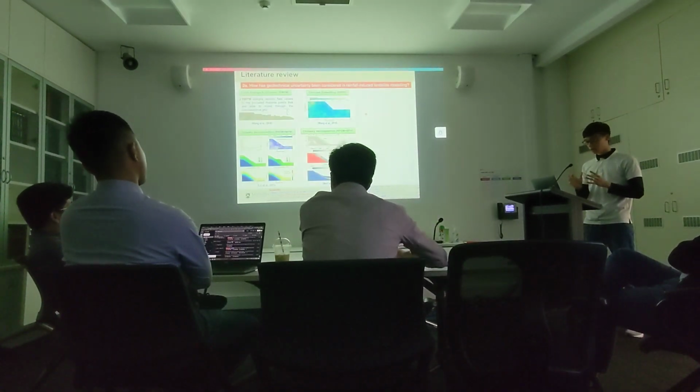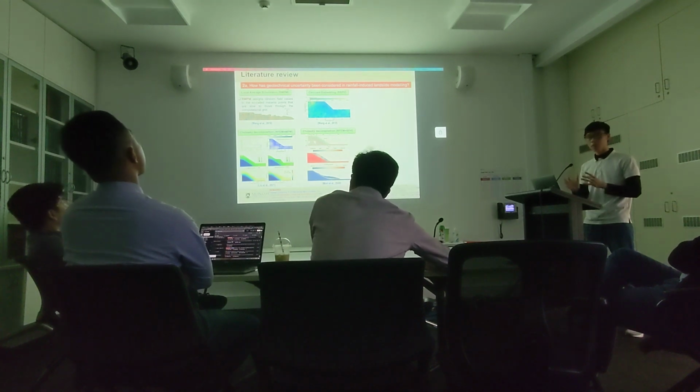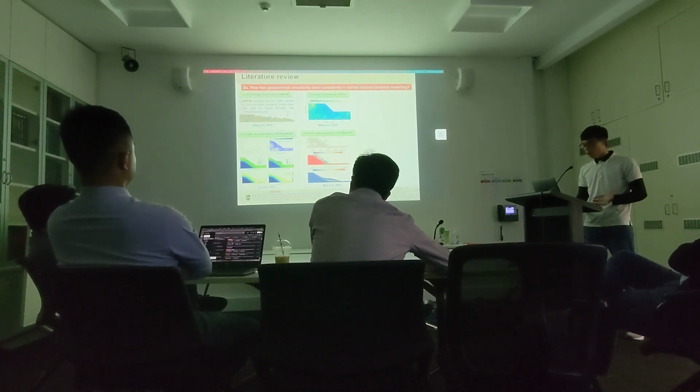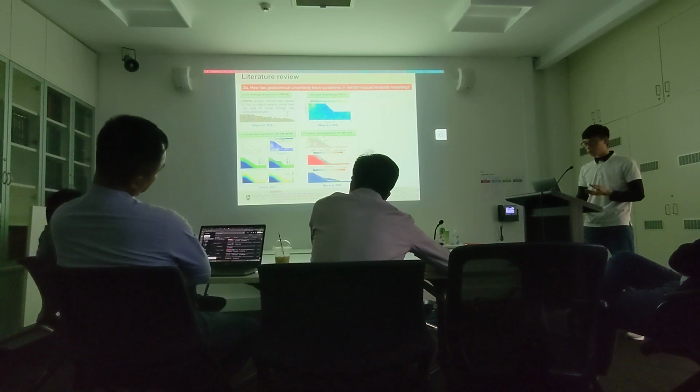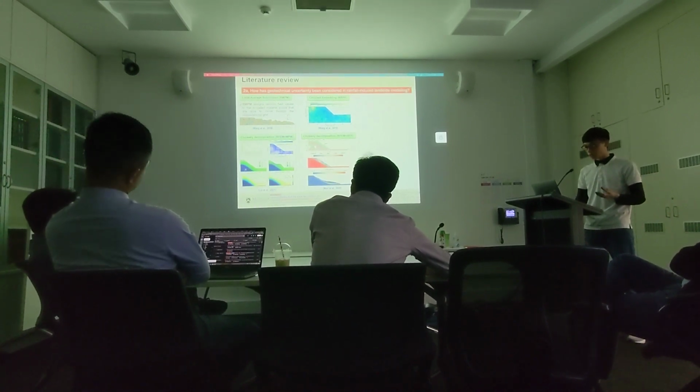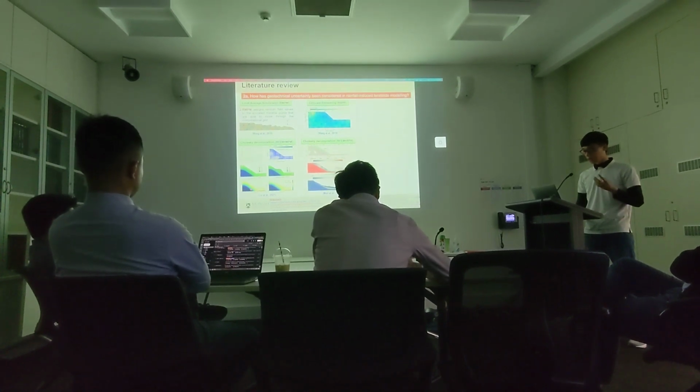When it comes to large deformation, methods such as MPM or SPH have already incorporated the random field, but currently they are used for granular flow without considering rainfall. So when they want to deal with rainfall landslides, they still use the random field from the finite element method. After analysis, they assign the information to the material points and particles in the SPH.